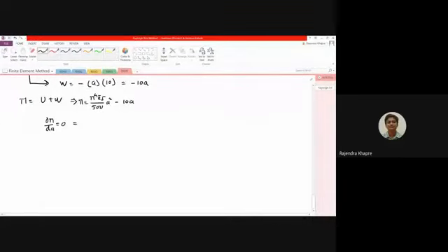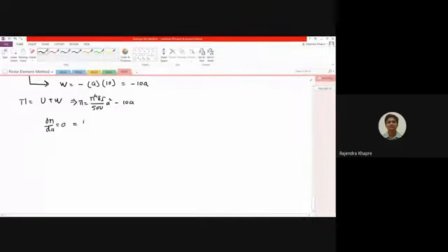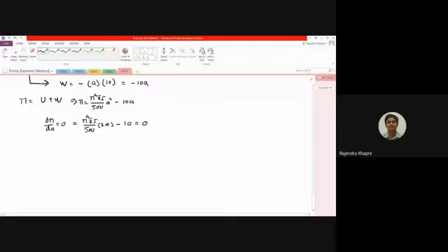So if you go for a derivative of this, so this will come outside. So π to the power 4 EI divided by 500, and this will become 2 times A, minus 10, equals 0. So you can take this side over here and you can simply find out the value of A. Okay, so can anybody tell me what is the value of A, please, by substituting the value of EI? E और I पूरा ये करके बताओ A की वैल्यू कितनी आ रही है?